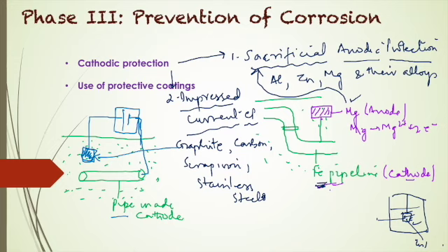In galvanized steel, zinc is coated, is the coating metal, and steel is the base metal. So zinc is more anodic. It is attacked, it is corroded, leaving the underlying cathodic iron or steel unattacked, even if it is exposed when pores or breaks or continuous discontinuities occur in such anodic coatings. So iron or steel is not corroded till the time all the coating of the zinc has been consumed.